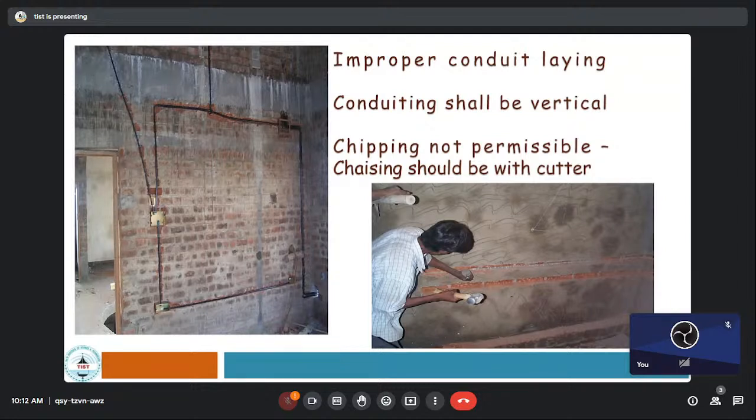Because you should understand that the load transfer of any civil engineering structure is from one member to the other, and it is compressive in nature. Once you have a big horizontal gap there, that layer is the weakest layer. So there will be more crushing over there, and a tendency of forming more and more cracks. So if you want to do any conduit works, don't go truly horizontal, go inclined.